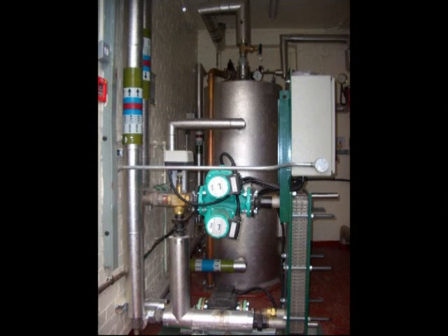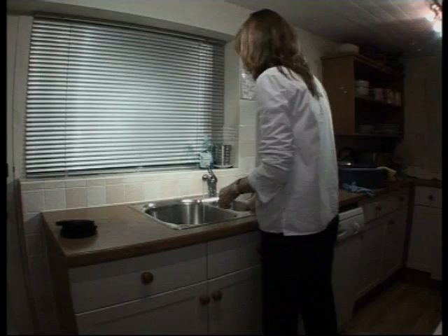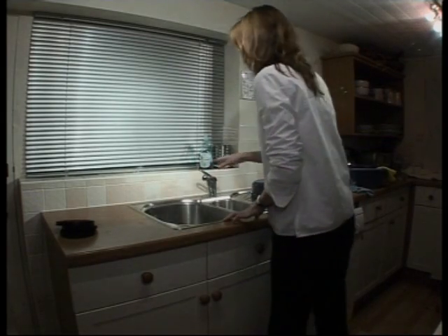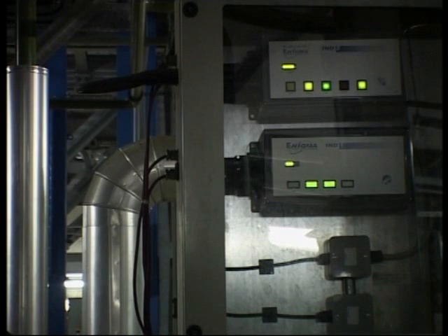A softener route should remove all the calcium carbonate scale, but some people say that perhaps they wouldn't want to then drink that water, and with things like polyphosphate dosing devices, by comparison, you wouldn't want to drink the water. Electronic conditioning devices condition the water, they don't really change the chemical composition, hence the water's treated but still safe to drink.